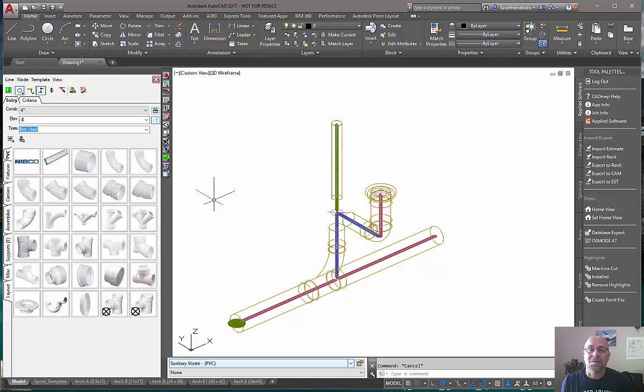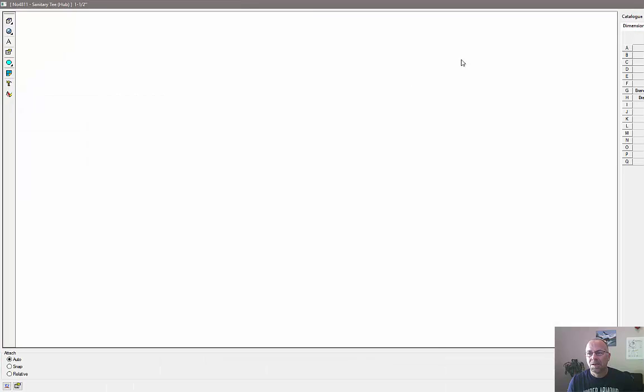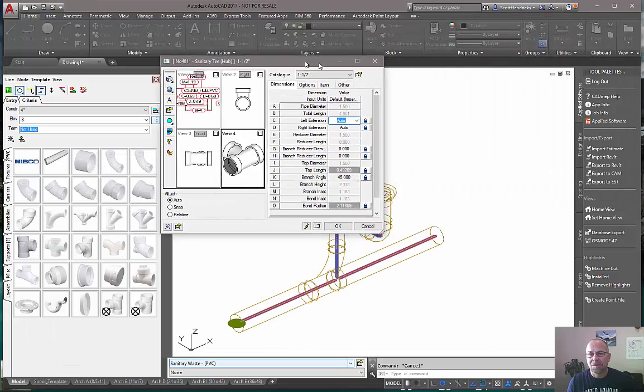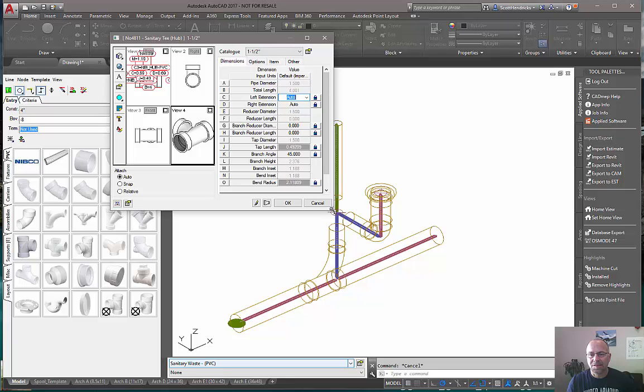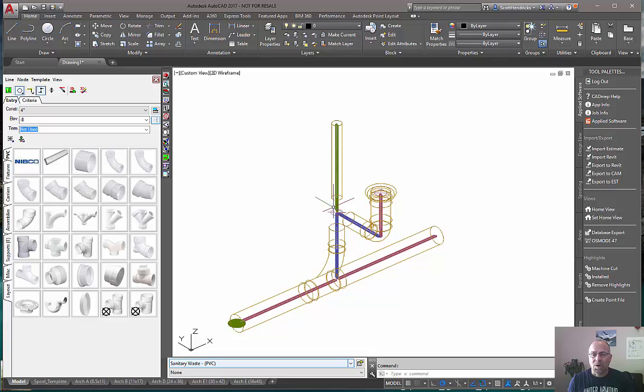it doesn't fill. And the problem is that this Santee doesn't come in that size. It doesn't come in a 3 by 2 by 3 size. So what it requires is for it to have a bushing, but it doesn't know to look for the bushing. So that is where